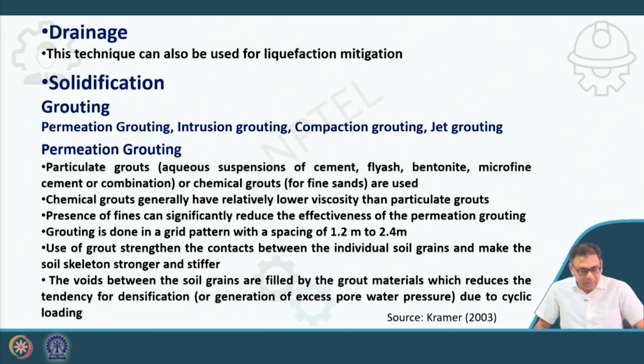Okay. Now, the next one is the drainage. So, this technique can also be used for liquefaction mitigation, and at a later stage I will discuss in detail about this drainage technique. Okay, now we will come to the solidification. So, solidification can be done by grouting. Okay. So, there are different types of grouting techniques: permeation grouting, intrusion grouting, compaction grouting, and jet grouting. About compaction grouting I have already discussed. Now I will discuss the other types of grouting.